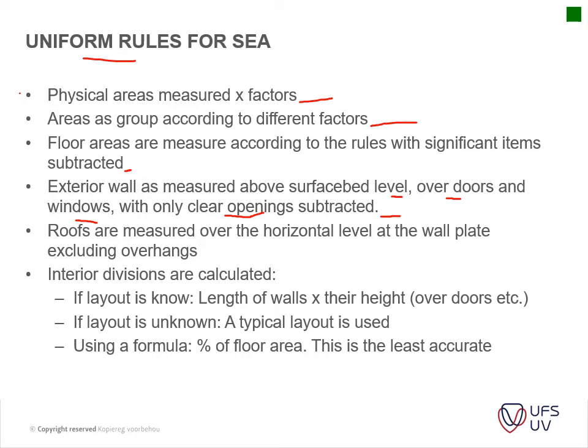Okay, roofs are measured over the horizontal level at the wall plate overhangs. So please take note of this. This is very important. Roofs are measured over the horizontal level. Okay, exterior divisions are calculated if the layout is known.